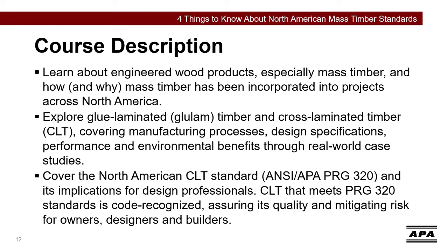Today we'll learn about engineered wood products, especially mass timber, and how and why mass timber has been incorporated into projects across North America. This webinar will explore glue-laminated timber and cross-laminated timber, covering manufacturing processes, design specifications, performance, and environmental benefits through real-world case studies. We will also cover the North American CLT standard and its implications for design professionals. CLT that meets PRG 320 standards is code recognized, assuring its quality and mitigating risks for owners, designers, and builders.